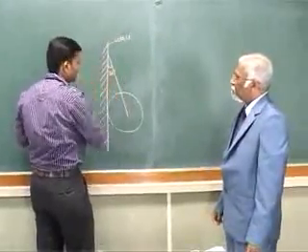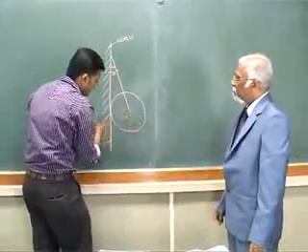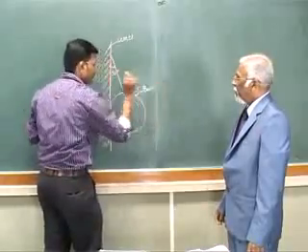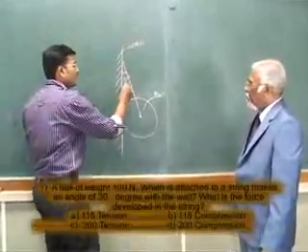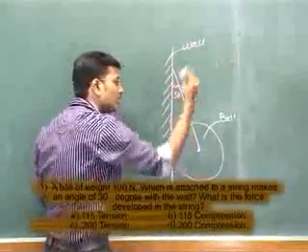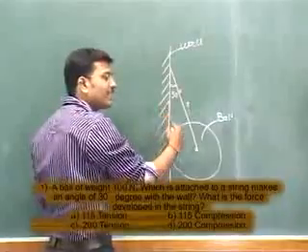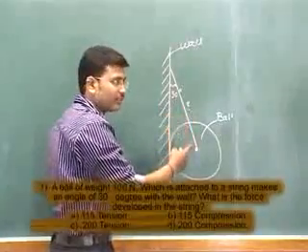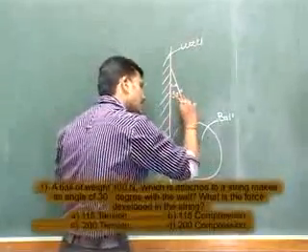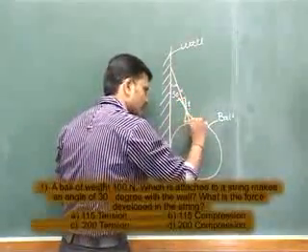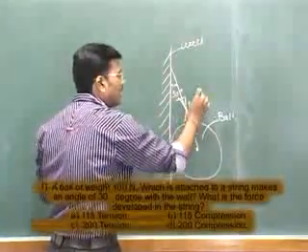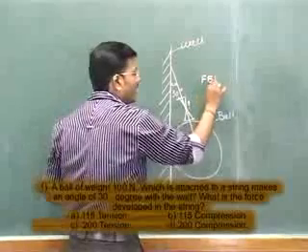So this angle is 30 degrees and it is attached at center. So this is your ball, and they are asked what is the force which is developed in this string. First of all we have to decide whether it is tensile force or compressive force. Since it is a ball, it has its own weight, it will develop a tension in a string. So tension in a string is shown like this, and we have to draw a FBD, free body diagram of